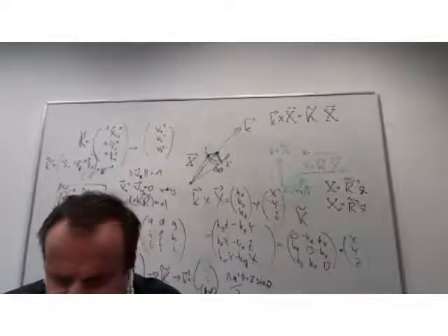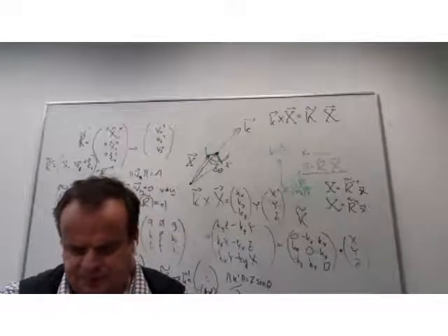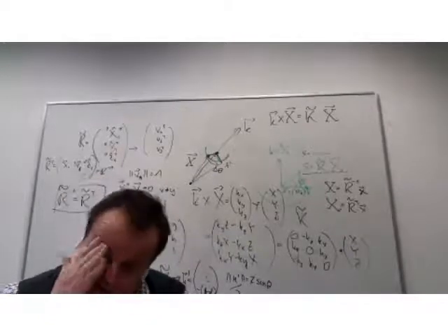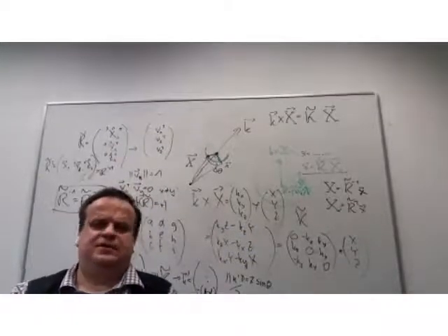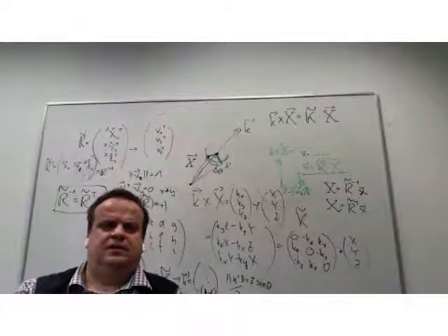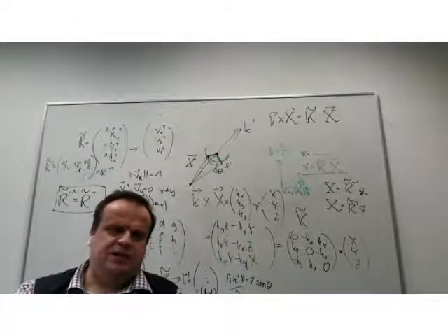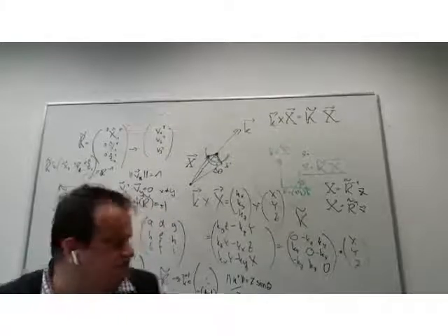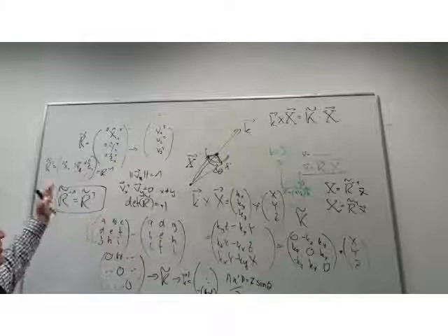So here we have exactly this axis angle representation, and usually the axis angle representation is very difficult to use in operation. So if you want to add angles, add one rotation to the other. A sequence of rotations as a matrix representation is just applying the rotation from left.